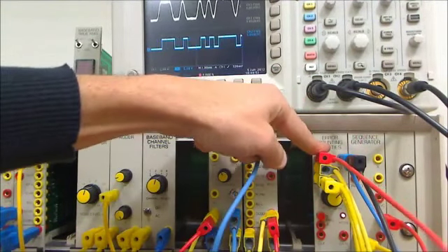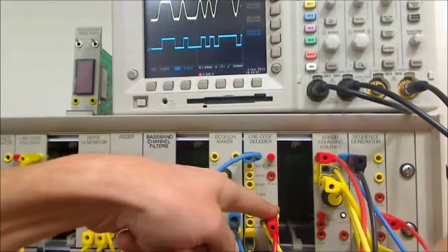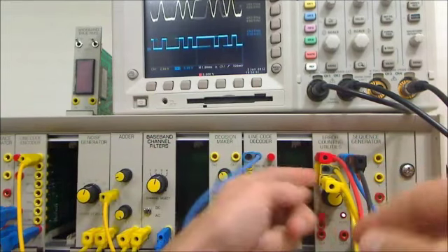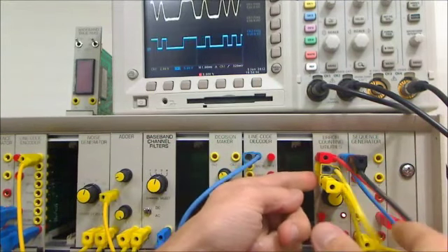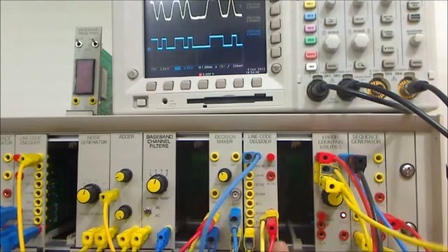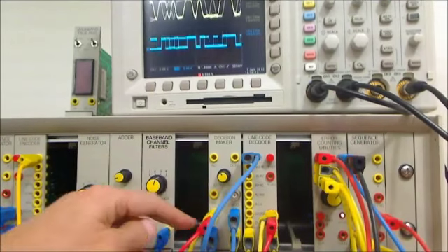So we connect the sequence generator to the error counting utilities. The second input comes from the digital output of the line decoder, and we also need a clock, which acts as a gate. That signal comes from the output clock of the line code decoder.